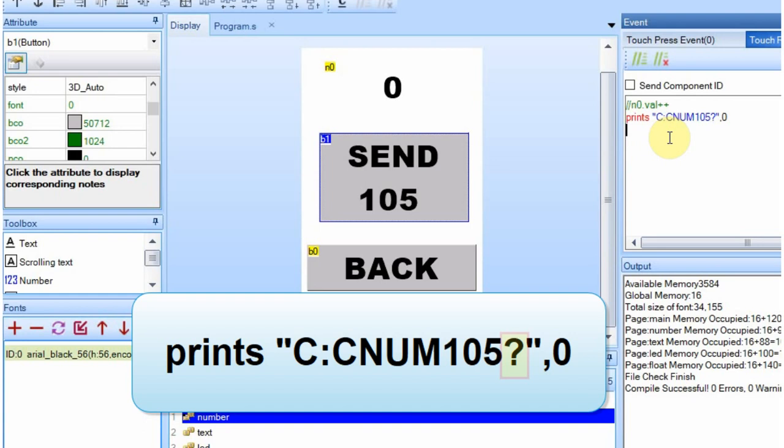That way the Arduino will know when the command begins, and it's also going to look for that question mark at the end. Now if you were going to use a question mark in any of your data for your value, then you'd have to come up with a different ending delimiter. But for this case, we'll be okay with that question mark. Sometimes if it gets really complicated, I'll put C?C as my ending delimiter, and then I have to look for that. But for this case, just to keep it simple, I'm going to have a 1-character ending delimiter, being a question mark.